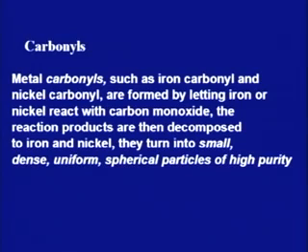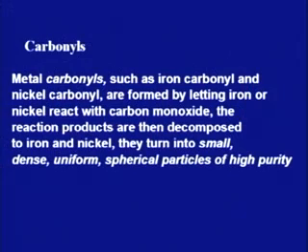The process is there, but the final emphasis is on the shape and the size of the metal powder that we are getting. The size is small and it is dense, it is uniform. Uniform means, as in atomization we have seen, the particle size is varying. Sometimes we may get bigger particles, sometimes smaller particles, but using this process of carbonyls we are going to get small, dense particles. The size of the particles will be pretty much uniform, the shape will be spherical, and these will be particles of high purity.